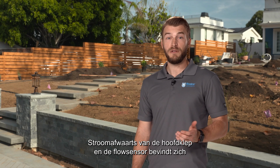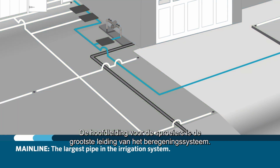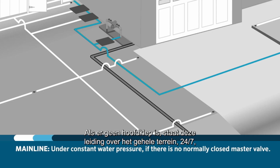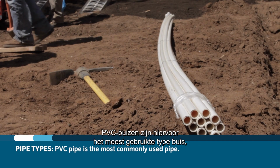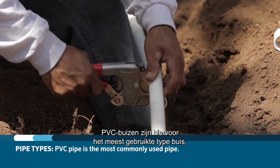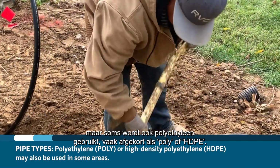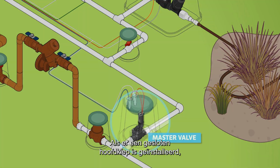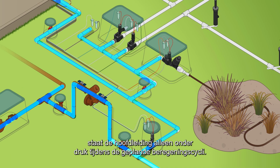Downstream of the master valve and flow sensor is the sprinkler mainline. The sprinkler mainline is the largest pipe in the irrigation system. If there is no master valve, this pipe is typically under constant water pressure at all times throughout the entire site, 24/7. The mainline delivers water to each of the zone valves throughout the irrigation system. PVC pipe is the most commonly used pipe for this, but in some areas, polyethylene, also known as poly, or high-density polyethylene, or HDPE, might be used. If a normally closed master valve is installed, the mainline only remains under pressure during scheduled irrigation cycles.